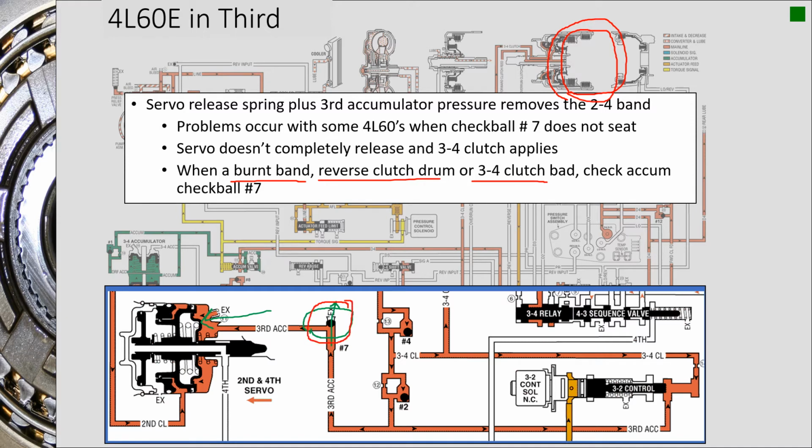A lot of issues also arise where the input shaft fits into the input drum; the splines can leak out. When you're air checking this, the 3/4 piston is the one on the very back, so there's not much aluminum. If you take a look at this shaded picture, the amount of aluminum that exists between the splines and the 3/4 cavity is small, and that fluid can squirt right out through there.